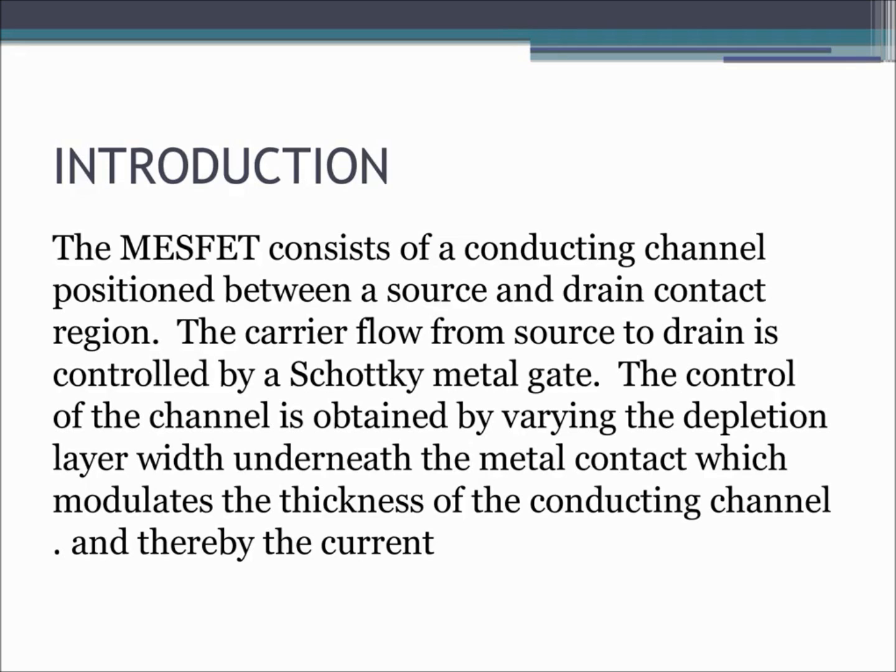The control of the channel is obtained by varying the depletion layer width underneath the metal contact, which modulates the thickness of the conducting channel and thereby the current.